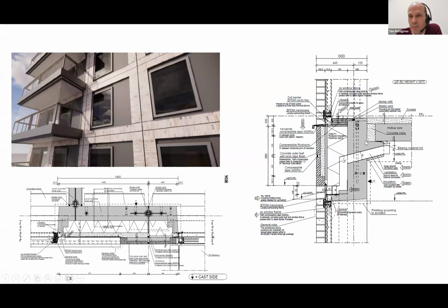And it's all held up by these small corbels that sit in this area here to pick up the prefabricated concrete slabs. There is then a small screed / concrete binding layer that ties in all of the different panels together. With this solution, you obviously have to design in serious coordination with the MEP contractors beforehand, because when they come on site, you've already got the built-in ducts that go through the facade. All of this has to be early stage design.